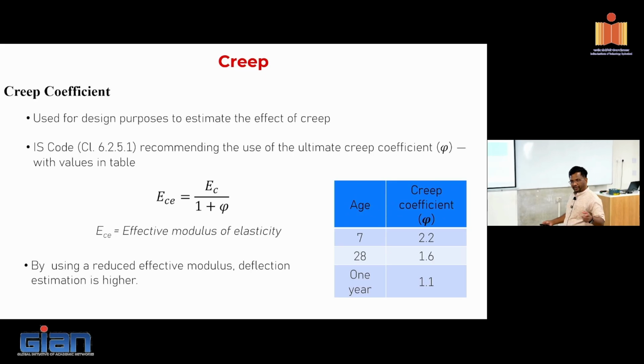But in fact, we were involved in a couple of projects in Dubai. The major problem happened because they started removing the formwork early. At 14 days, they started removing formwork and the slab started caving in. See, strength I can put in by multiple ways, but deflection, how do you recover? It's a major problem. People think that removing the shoring is a very important thing, and not many people understand that. So always you have to test cubes before you remove the formwork shoring.